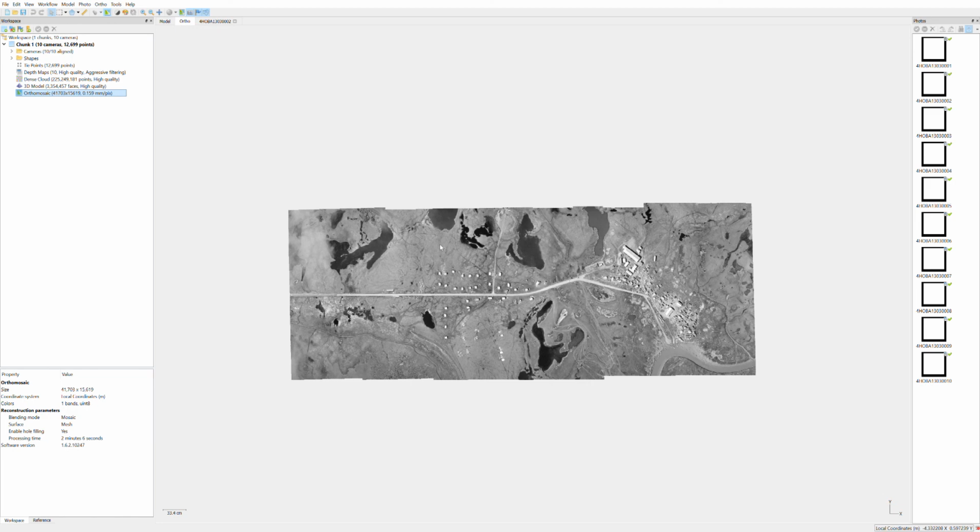I wouldn't go overboard, because the more georeference ties you add, the more it can actually warp and skew the image, which should be pretty orthorectified. But keep in mind, since we didn't have that overlap, especially around the edges, those areas probably won't be very well ortho. So I wouldn't use, probably like, 60 or 70% from the edge of the image. I can use a selection to say I'd probably only focus on this part of the image to do my georeferencing, and anything outside of that I just wouldn't trust, and that should save you some pain.